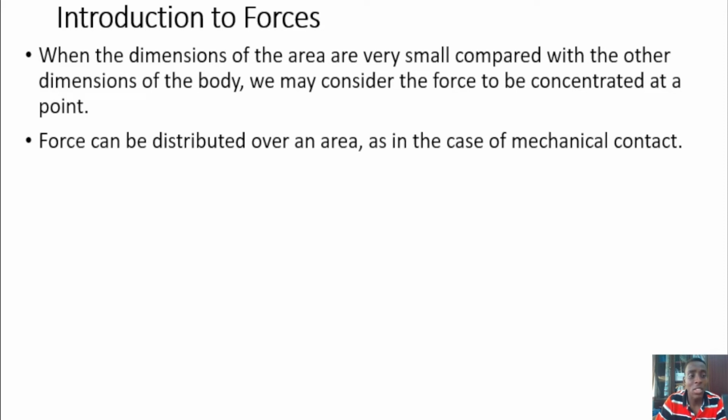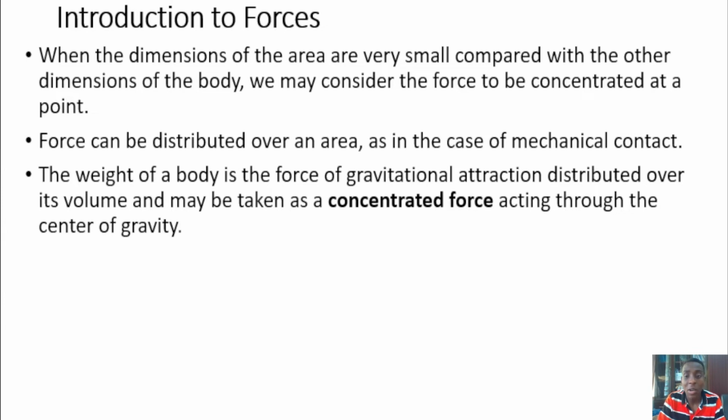However, a force can also be distributed. As a matter of fact, all forces are distributed forces in nature, because whenever two bodies are in contact, there is going to be an area of contact, as in the case of mechanical contact. The weight of a body is the force of gravitational attraction, in other words the gravitational pull you feel, and this force is actually distributed over the volume. However, in all our analysis, we are going to assume that weight is a concentrated force acting through what we call the center of gravity. There is a whole video which I have done on centroids and center of gravity.